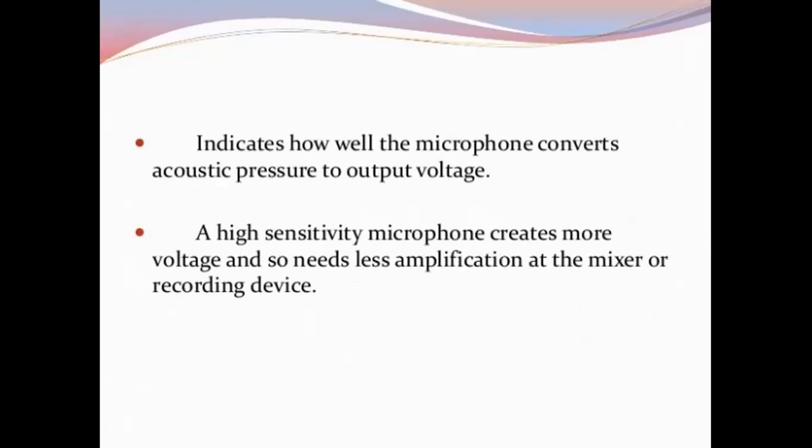Active microphones would typically have a sensitivity rating within the range of 8 to 32, and good active microphone sensitivity ratings are also between 8 to 32 mV/Pa. The high sensitivity microphones create more voltage and so need less amplification at the mixer or recording device.